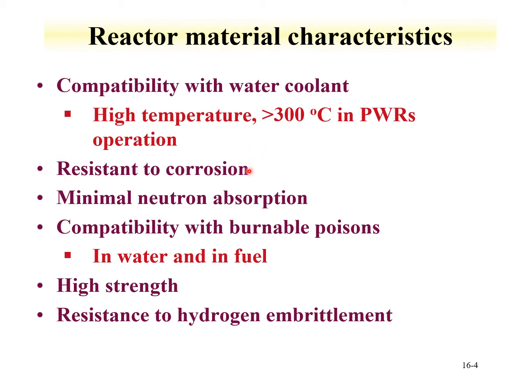For obvious reasons, you wouldn't want the material producing particles that then go into the reactor, or breaking and causing coolant or even the fuel itself to be released. They need to have minimal interactions with neutrons, since the neutrons are the driving force in the production of power through the fission process.